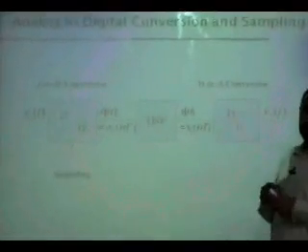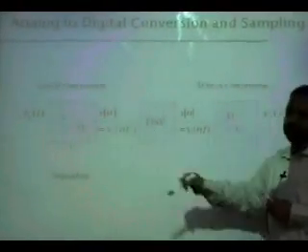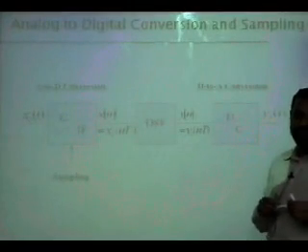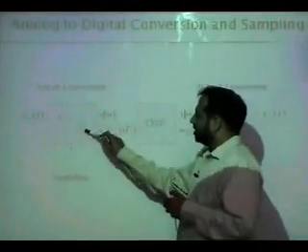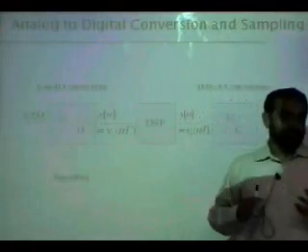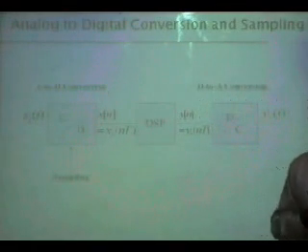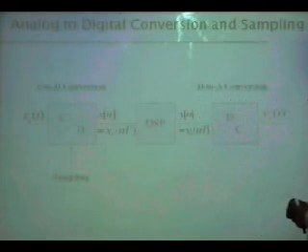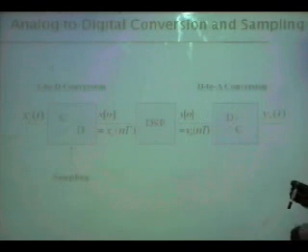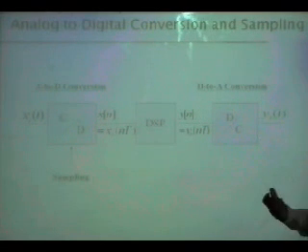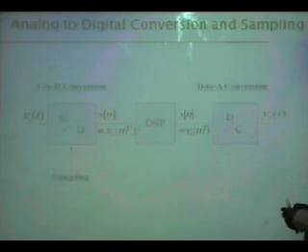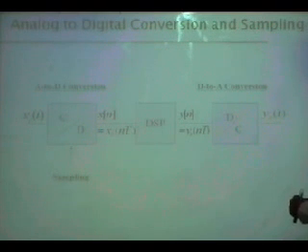If you make a mistake here or here, it's very difficult to fix. A mistake made while selecting an A to D converter will really hurt you in your system. And the same is the case if you don't appropriately select a D to A converter, that will also hurt you. So it is very important to understand the intricacies of sampling.